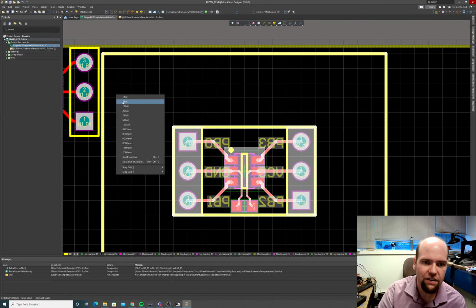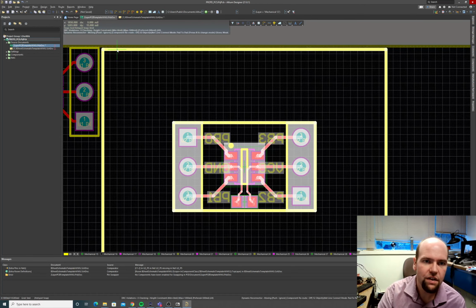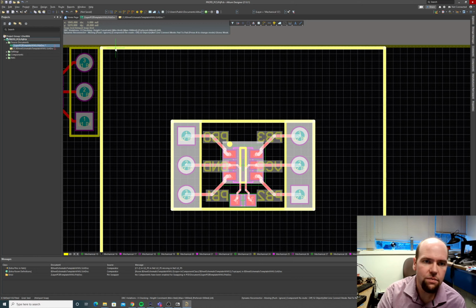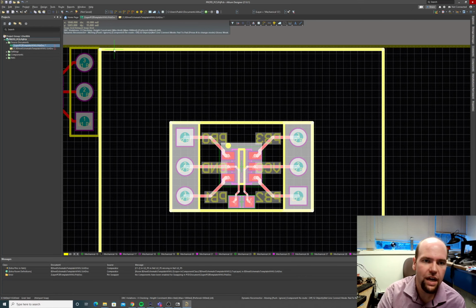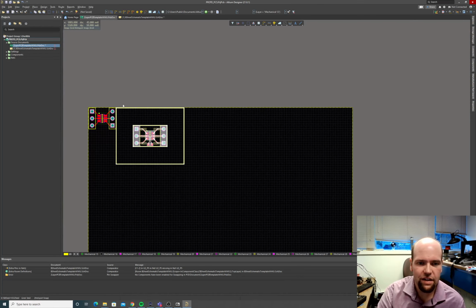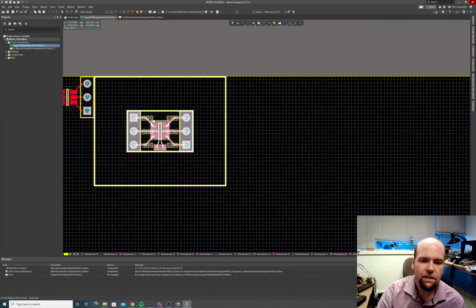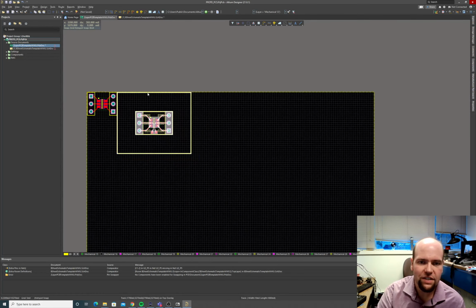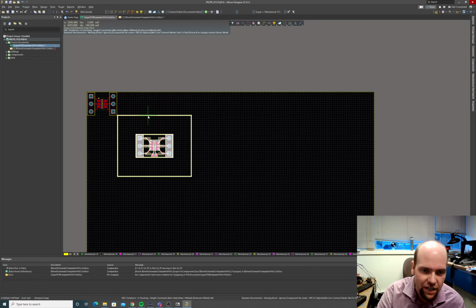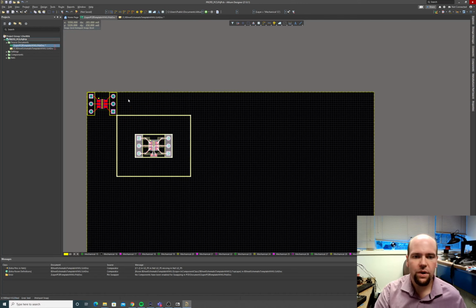So if I set my grid even to something tiny like 5, it's going to be fine. This would be okay as a part on a circuit board. I would be able to cut in between these parts. If I wanted to have this thing at the top, it doesn't even need a top space. But if I was trying to do this at the corner like this, and I had other parts in here, those parts on the edge can stay in there, but I need to keep around each of my components this sort of buffer space.